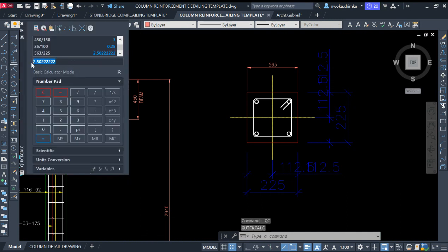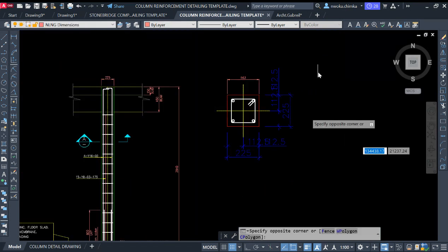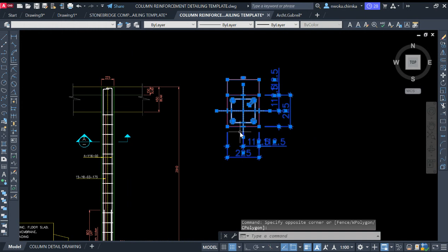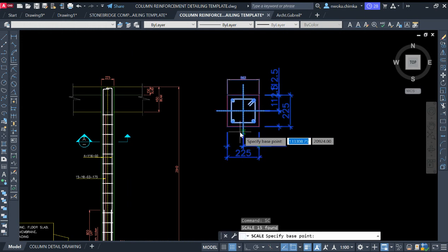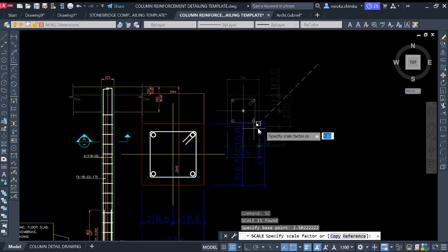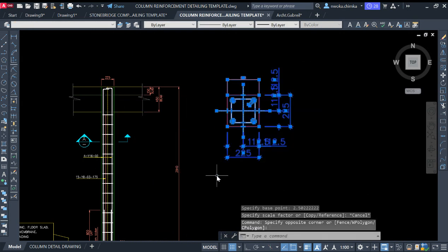So you'll copy this right now. Right click and take copy. Then close this, and select everything here. Then type SC for scale, enter, type any value first, remove it, and then paste the value which was scaled up, and then input it here. Sorry, do that again.